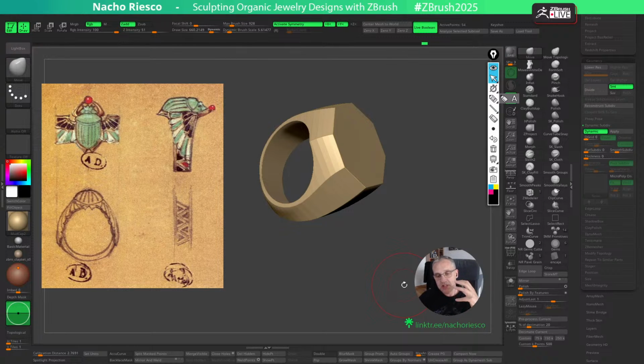But the option is to start with your geometrical shape with a cylinder in the middle just for making the hole, and then start playing around with the ZModeler with the different sides and the different vertices still matching. And once you have the forms, just for blocking the sides or the corners, start making different polygroups, creased polygroups, and then you can start subdividing, and that's it.